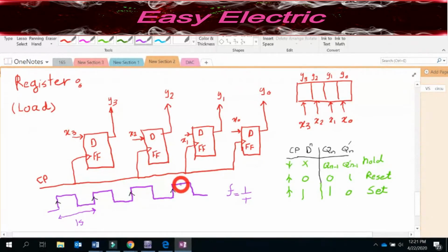So that means just in this rising edge, it checks the value, whatever you have here, loads it inside this register, keeps that until the next rising edge, which again double checks the input and sees what you are giving. Somehow this is the memory, right? The register is some kind of memory. You are able to keep these bit patterns inside this for a location.